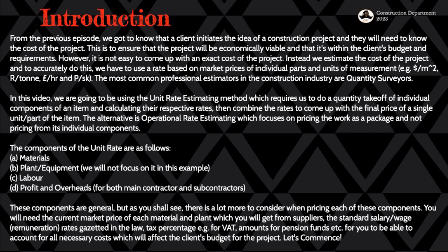If you see on the components of the unit rate, we are not going to be using the plant and equipment. We're not going to include it in our calculations because we're going to be assuming that the people are going to do the work of mixing the mortar. But with the concrete, it was going to be a bit difficult for the people, so we had to factor in the plant and the equipment, like the concrete mixer, the vibrator, and the like, so that at least we account for the machinery that will be used to help the labor in doing the work. So you can just read through and familiarize yourself with what we're going to be dealing with. Otherwise, let's move on to the quotation.